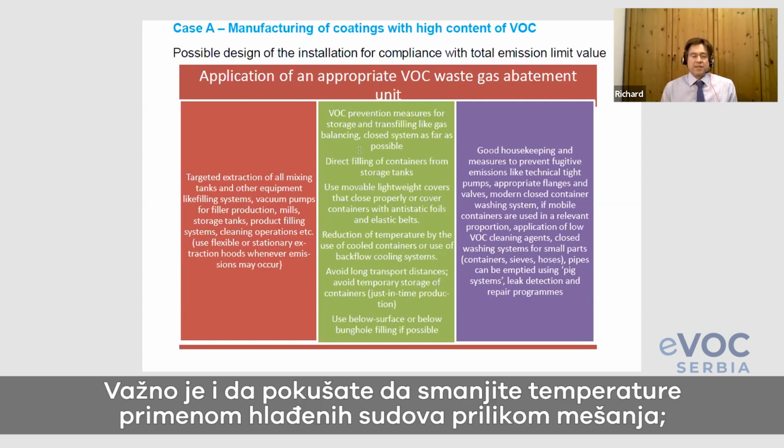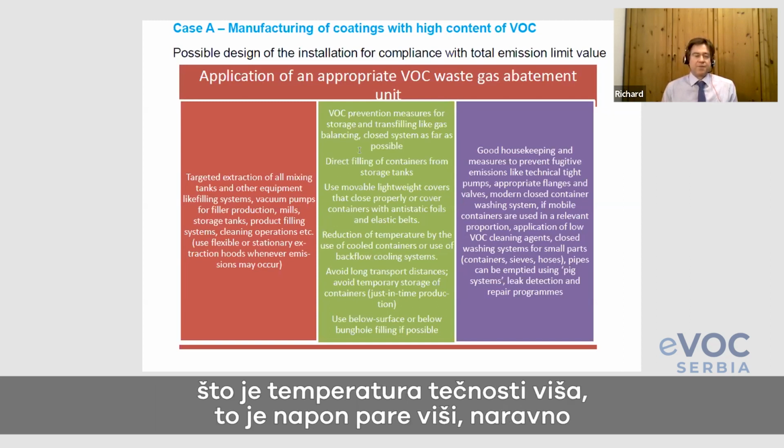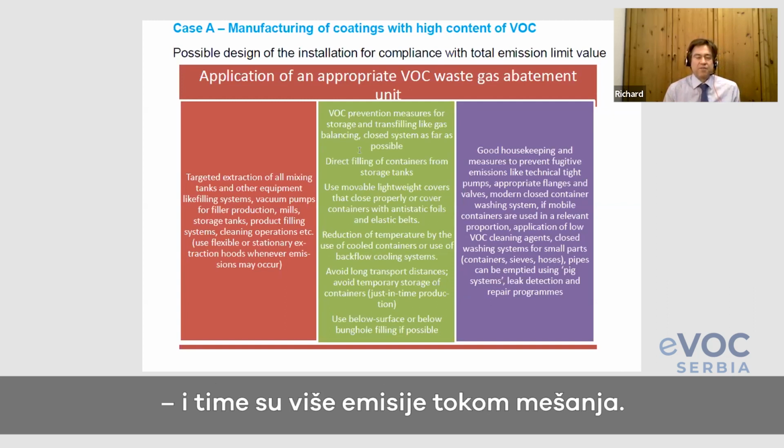Important, try to reduce the temperature by using, for example, cooled vessels when you do the mixing. If the temperature of the liquid is high, of course the vapor pressure will increase and you will have higher VOC emissions during the mixing processes.